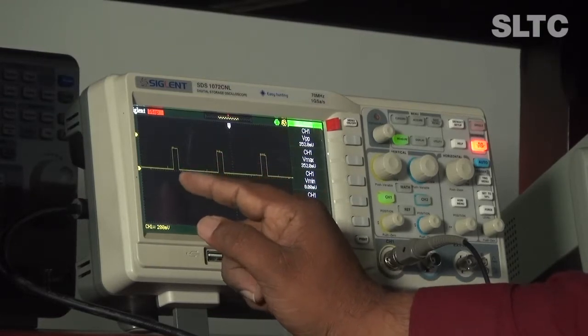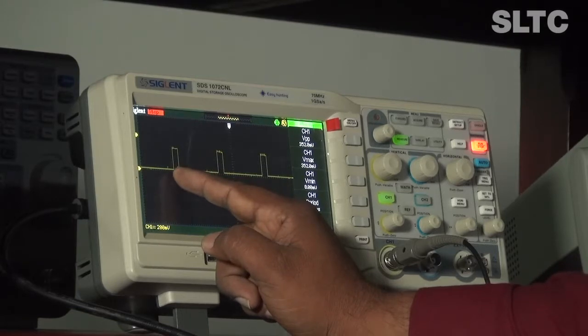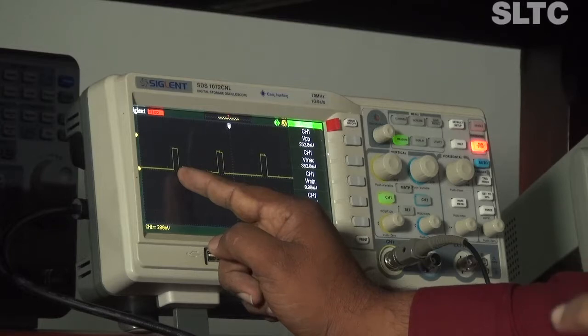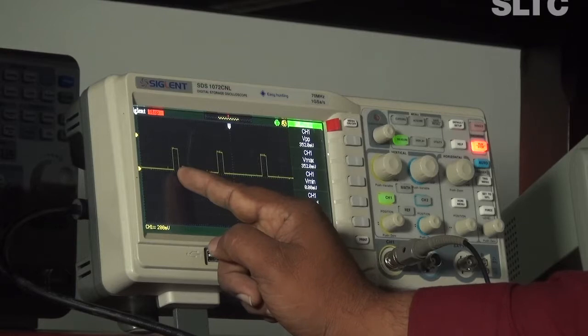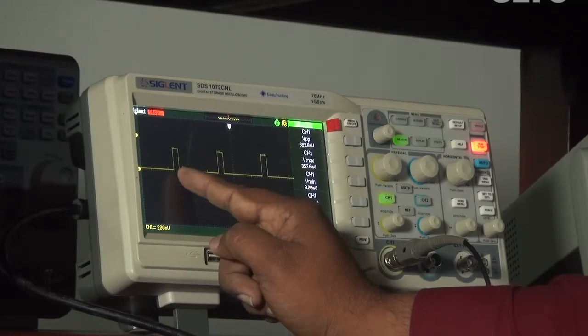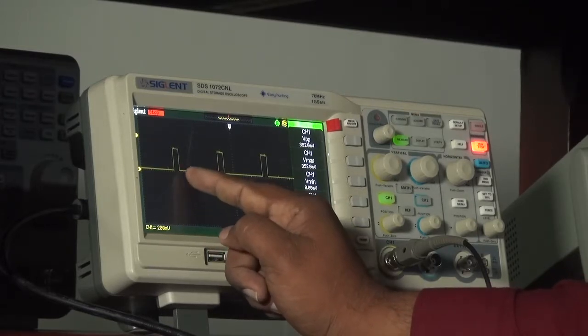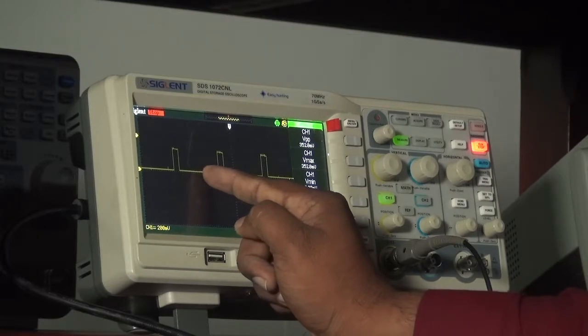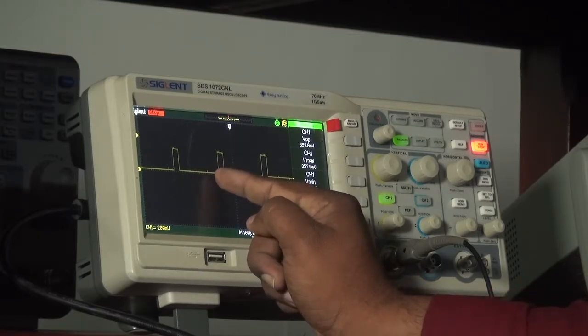At that time the multiplexer reads port 0 up to here. Then after a particular time, the address bit changes to 001, and the multiplexer will read the next port, the second user, but there is no information there. Then the third user, no information, the fourth user, no information, and so on up to the 8th user.